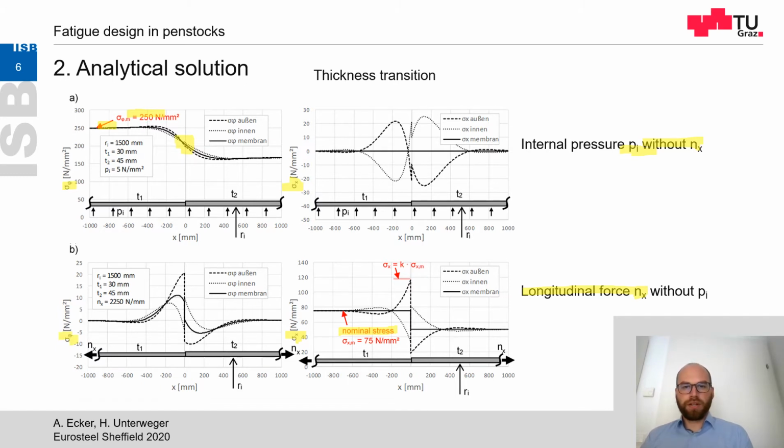And here an increase of the stress on the outside occurs at the thickness transition. This stress can be described with the load concentration factor K times the membrane stress.